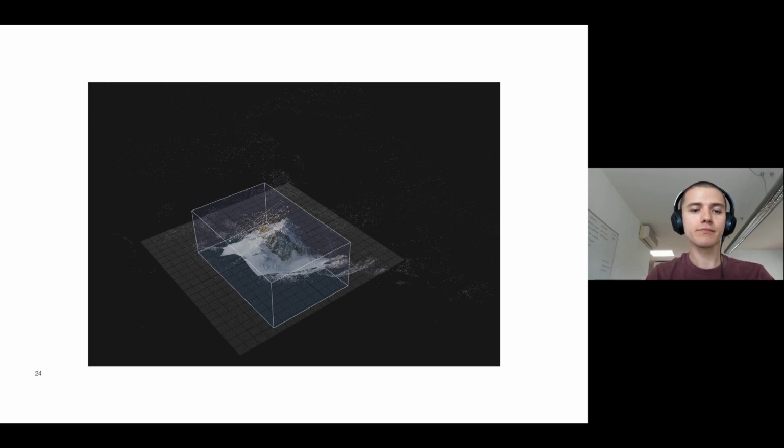Okay, so after our point cloud is ready, we can either go straight to the mesh generation or color the point cloud so we can have a general feel for the colors of our object. The process of coloring is generally pretty fast and straightforward. It's one of those steps that are not always necessary for the final mesh generation, but it's useful if you want to see a draft, let's say, of the model.